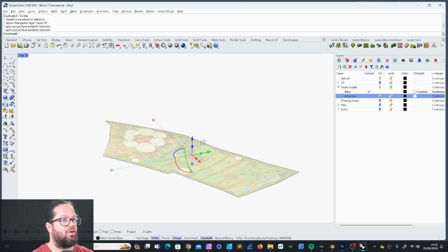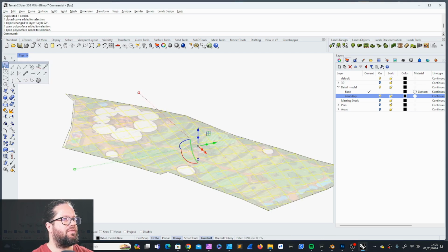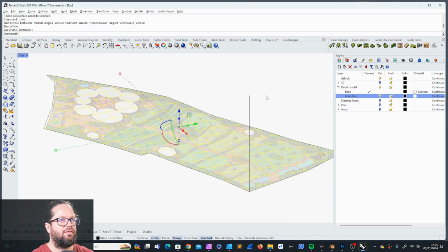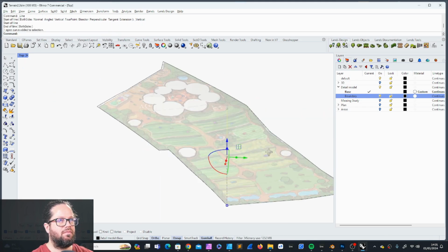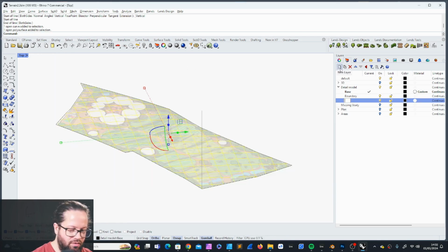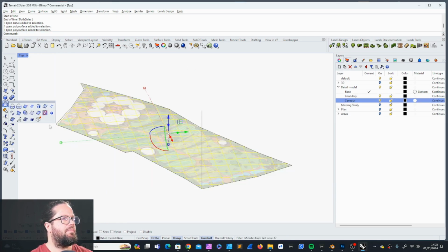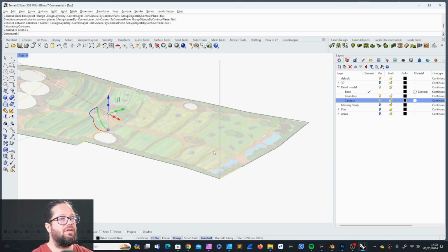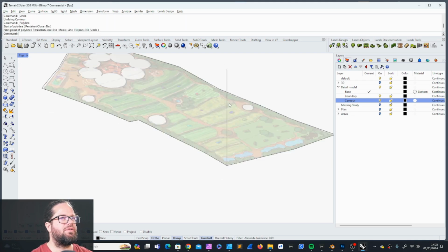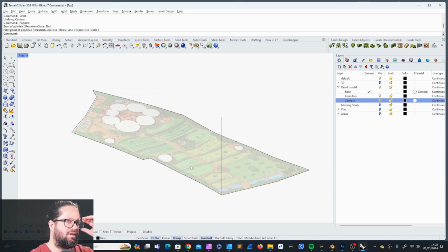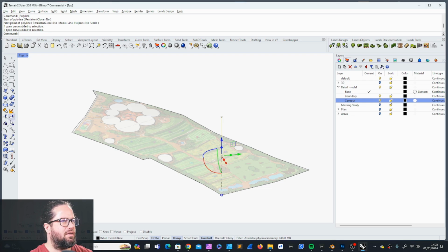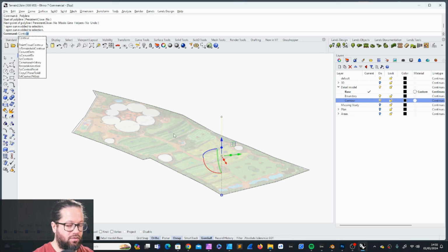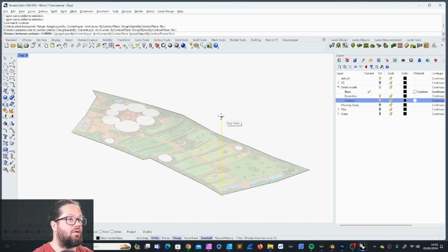I want to do a few more contour lines, so I have a better understanding of how the terrain looks. So I will just create a vertical line here. I'll make a new layer also. Take this, and by the way, there are so many different ways. I'm a bit of an old school 3D modeler. So this was every meter. By the way, I'm not 100% sure about the exact levels of this, so it's all going to be approximation. So actually, let's just use this as a 0 point. Contour again. Contour. Distance between contours. Currently we're in meters, 1 meter. Let's say I want to have 0.5.